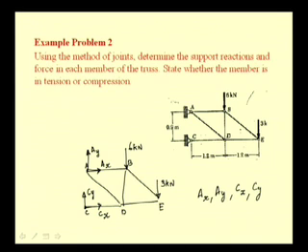But we know that for this truss to be in equilibrium, if we write the force summation equations, sigma Fx equal to 0, sigma Fy equal to 0, and sigma moment, let us say about point A, equal to 0, these three equations can be used to determine only three of these unknowns. So, how do we proceed?